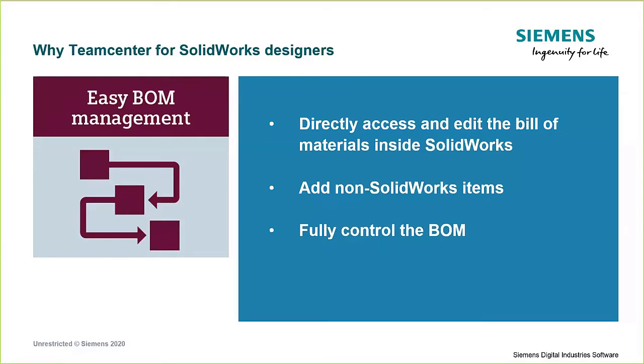And what we typically see users doing is they just put a part in SolidWorks, but they don't add any geometry to it. So it's in essence a blank, no-geometry part. Well, what about name BOMs? Name BOMs, you can generate those via Windows Explorer. But keeping that name BOM connected to your CAD BOM, once again, can be difficult and cumbersome. And perhaps that's why we see Excel is still a common BOM method of choice for SolidWorks design teams today, even though there's no connection to CAD.